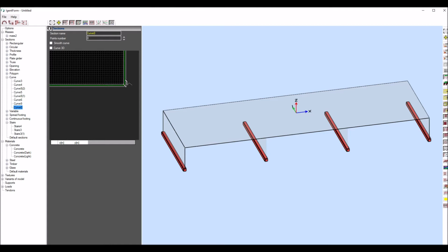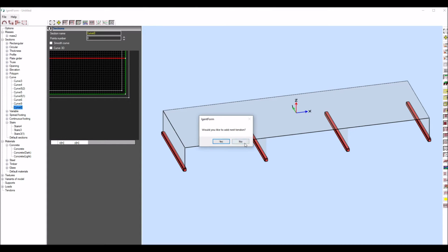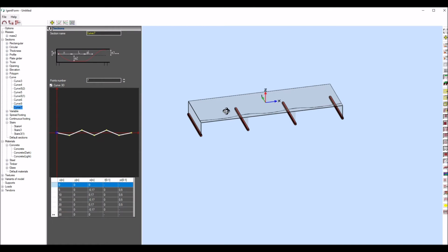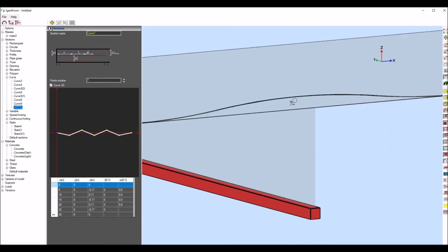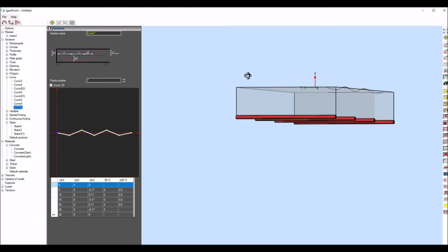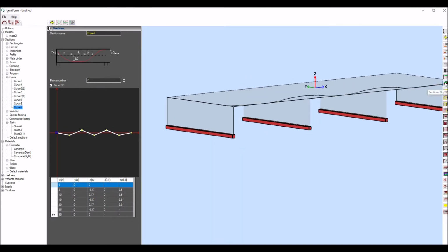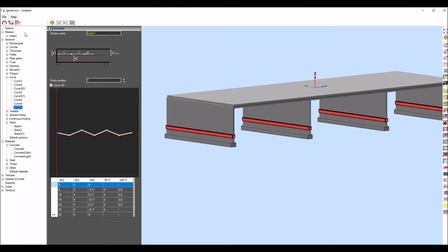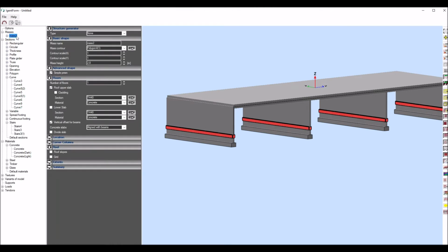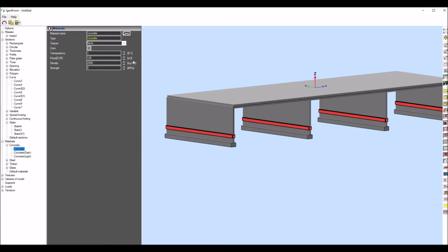When these edge points are defined outside the plate, the program can automatically cut such a tendon to the plate contour. It is recommended when contour edges are sloped. Tendons are located inside plates, so in a normal situation they are not visible. To make it possible, it is necessary to change one of the material properties, namely transparency. So, if I do it for the plate material, then both plate and tendons are visible on the geometrical view.